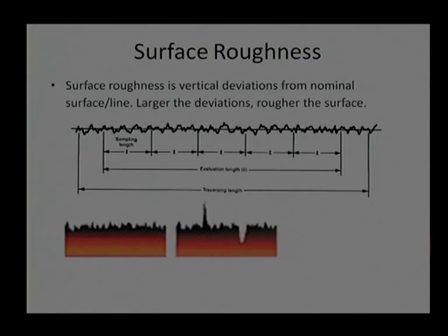If there is a possibility of fracture of this sharp peak at the start itself, then there is no problem, we can choose this surface roughness and this surface also. However, to implement this kind of approach, we generally use running-in time between the components. We know that when we buy a new car or automobile, the company instructs us to drive that vehicle at a lower speed, so that the running-in or bedding-in time is over at the lower speed and does not cause a catastrophic failure.